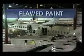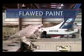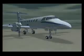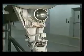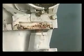This brings us to another factor to be considered in designing your corrosion control program: flawed paint. This can be anything from poorly applied or maintained paint schemes to nicks, scratches, and other flaws which occur during the operation or service of an aircraft. Areas prone to paint damage during operation, such as the wheel well and landing gear areas, should be checked regularly for chipped or missing paint. This and any other damage to the paint system should be repaired promptly with touch-up paint or an effective corrosion preventive compound.